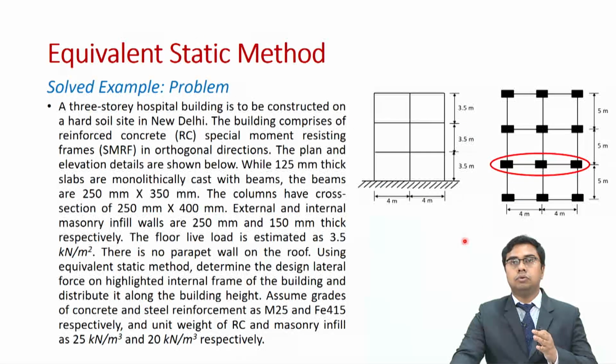Here we are supposed to design a 3-story hospital building which is to be constructed on a hard soil site in New Delhi, for which we need to estimate the design seismic load. The building comprises reinforced concrete special moment resisting frames, that is SMRF, in the orthogonal directions, that is, we have SMRF in direction x as well as direction y. The plan and elevation details are shown over here. This is the plan, this is the elevation,